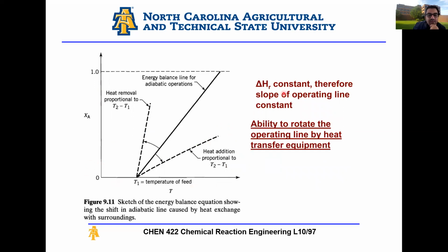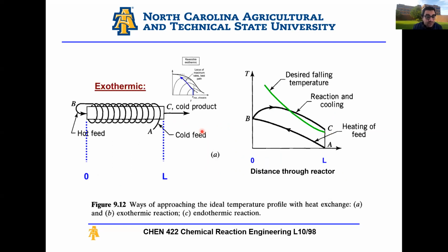XA versus T, you have your enthalpy again. If I add heat to my system, I can shift my system away from adiabatic conditions and I can move it towards isothermal conditions. You can basically rotate the operating line using heat transfer equipment. Okay.